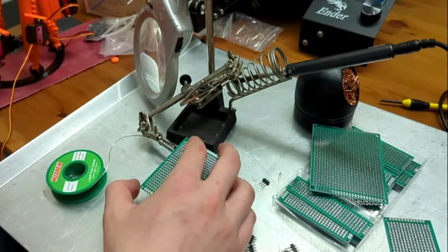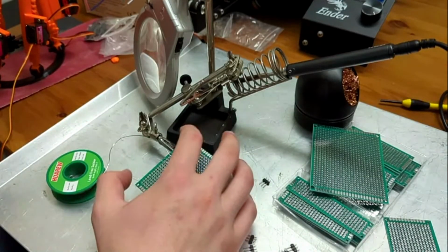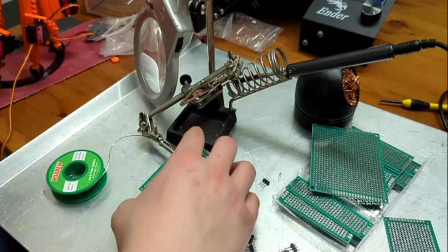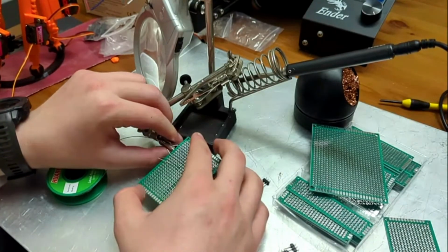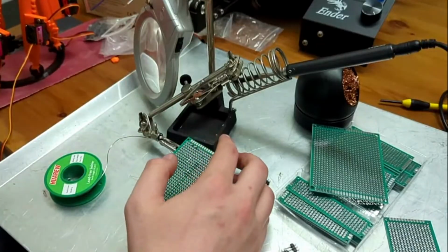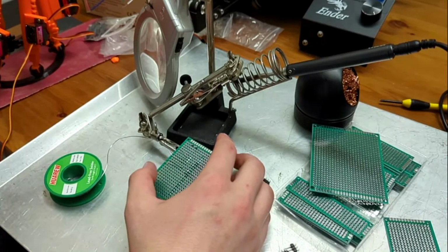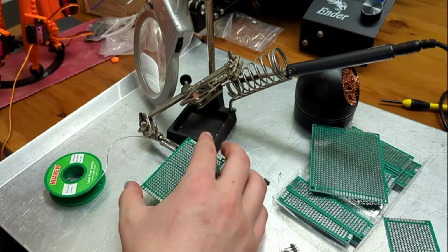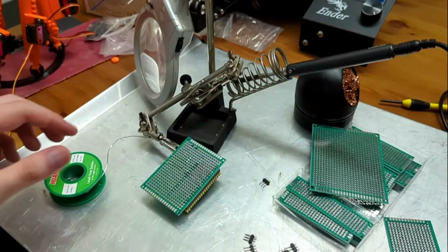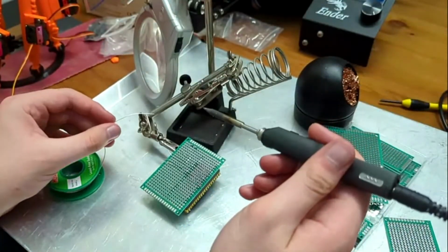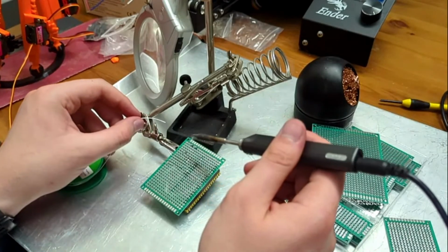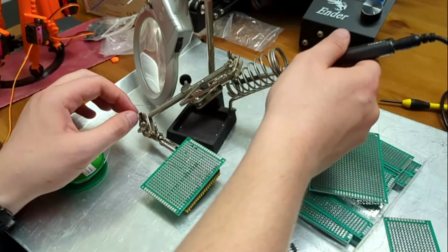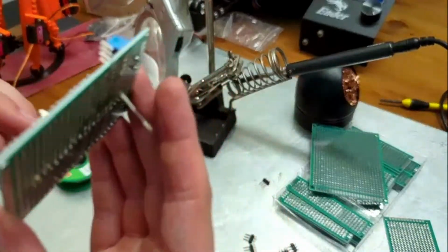One of the important things is I don't solder it too crooked, which as it is now, it is very crooked. But I think that right there is pretty good. That's looking good to me. And then what I'll do is I'll just solder one joint, only one of them. There we go. And that way, I'll take it out, and that one solder joint's plenty to hold it.